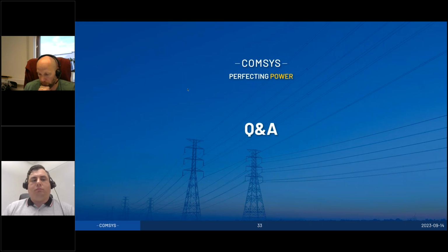And this is the same as you had before, because when you tune the system manually, you also get a fixed tuning. However, we have added support so that the auto tuning function can actually be triggered. Technically speaking, we have the possibility in the software to add functionality in the future where you have a completely dynamic tuning that could run all the time. But for this release, it's a fixed tuning. I would also like to mention that when the tuning is done, you will actually see the result. So if you want to use the auto tuning as a good starting point and then manually tweak it, you can also do that.